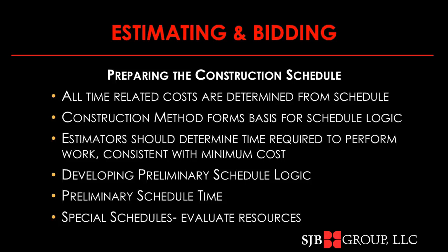You need to identify milestones that are interim required completion dates that may be stipulated in the contract by the owner. The more of these interim required dates that are present in the contract, the more risk it creates for you to meet each and every one of those time requirements. And in doing your schedule, you need to also consider the availability of materials. Are you going to be able to get asphalt in the winter? And can you get aggregate in the spring when floods are happening on the river? Those types of things.